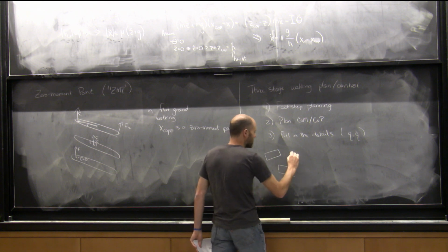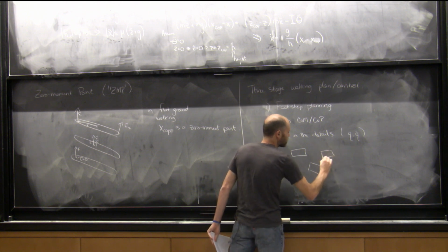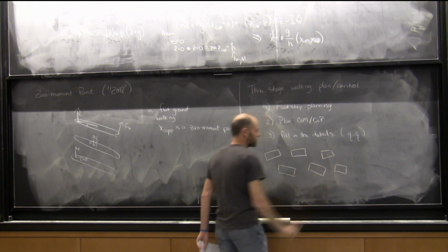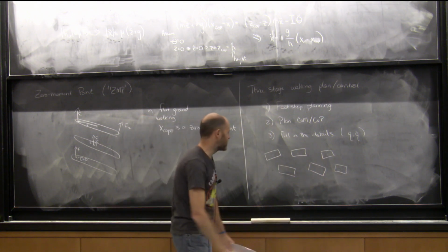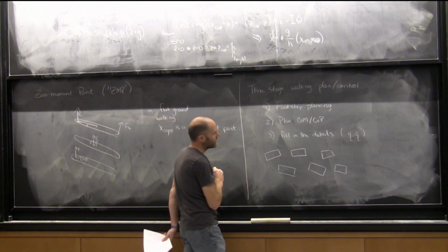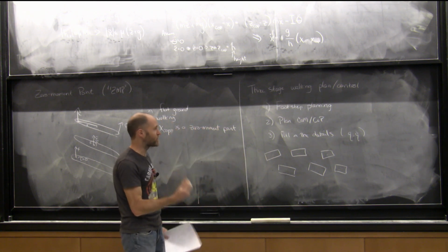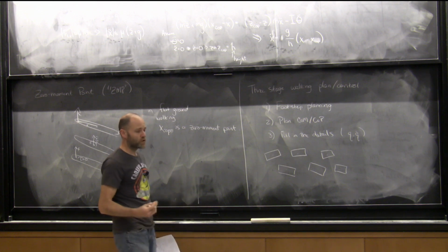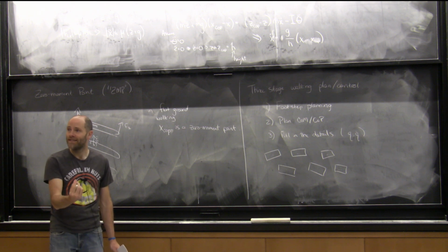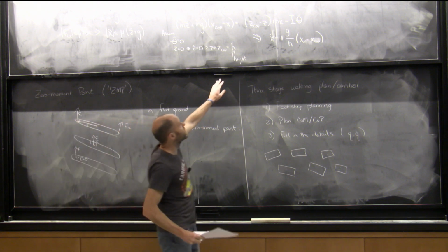So footstep plan, if I'm looking down from above now, I've got some feet that are walking along. This is my left foot, my right foot, okay? At different times, this is like the, follow this way to find the gorillas at the zoo. Footsteps down from the top, okay? There's a couple things we know about summarizing the ground reaction forces as the center of pressure. So first of all, the center of pressure has to be inside the convex hull of my ground reaction forces. That should maybe be intuitively clear.